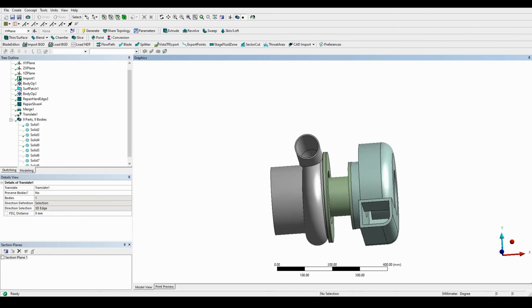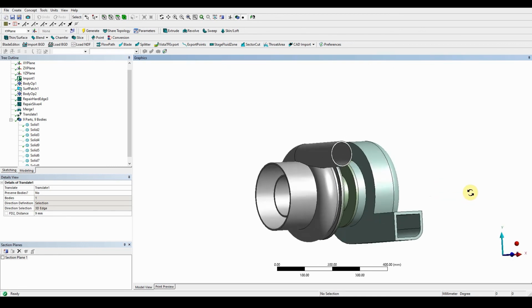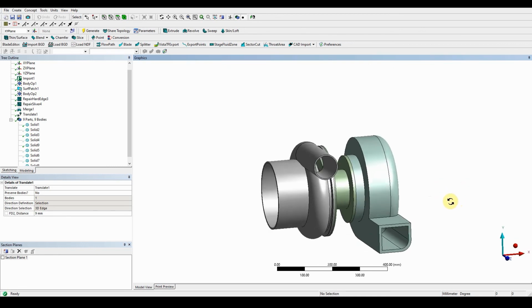We can now look at removing some of the small gaps between the center housing and the turbine housing. So again, what we need to do is use the distance finder. It's a gap of 2mm. So we use the extrude to close this face by extruding face 1, highlighted in the image on the workshop. So again, here what we're looking for is this section here.